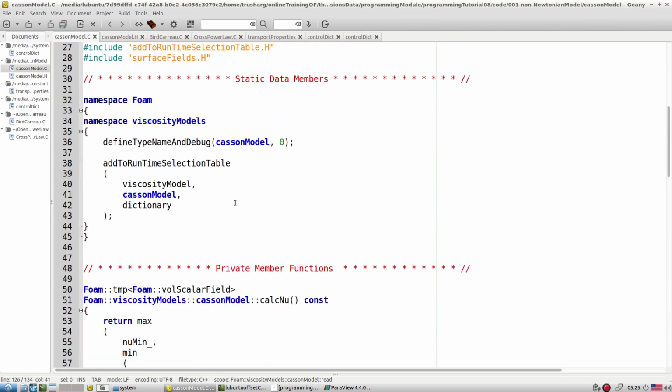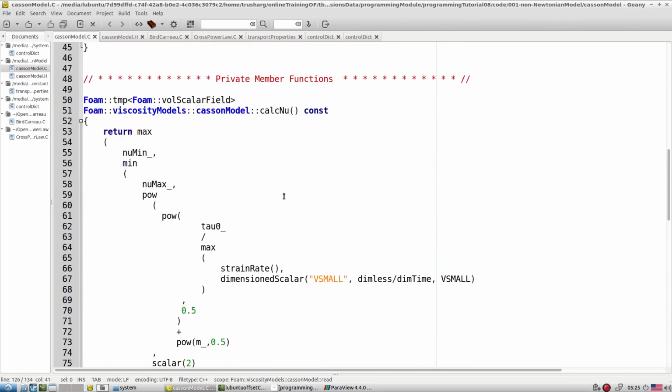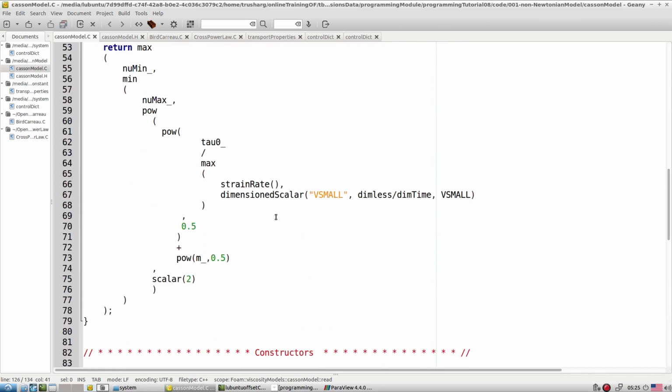So this is a very simple way to incorporate a non-Newtonian model inside our new library. For that, what we did: we first took the template out of the src folder, and without modifying anything we just compiled it. While compiling, we may have to resolve the options file in the Make folder to resolve the dependency. After resolving the dependency, our template is ready to go, and then we start developing new code inside it.